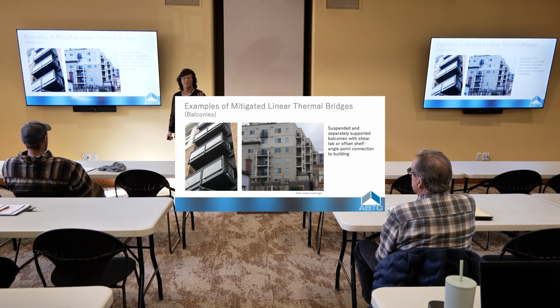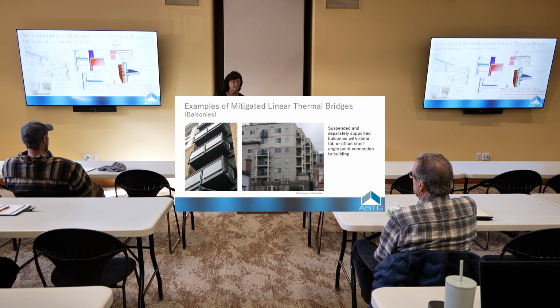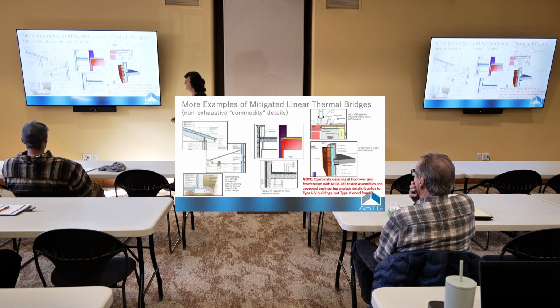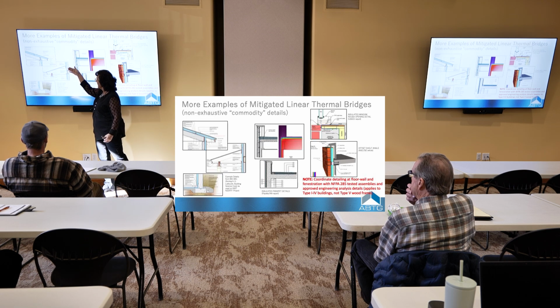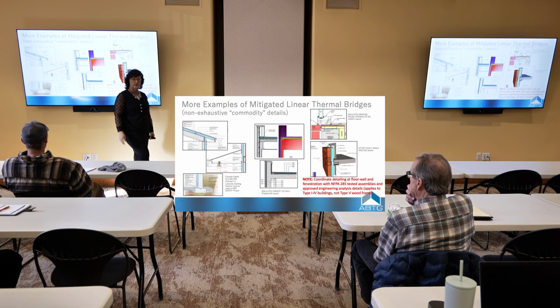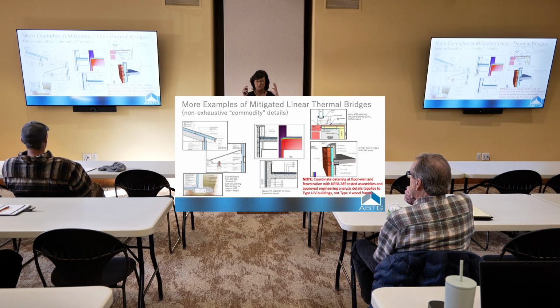Instead of building a porch that is open to the inside, you build your wall and then build the porch or the roof cover or the patio cover or whatever. It's just wanting you to think about adding these things after the fact instead of penetrating the thermal envelope for them. And so it's a great guide.